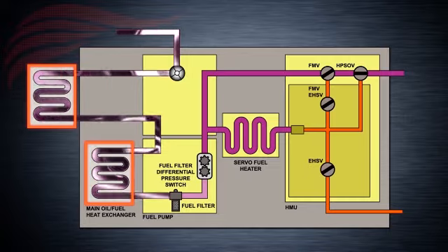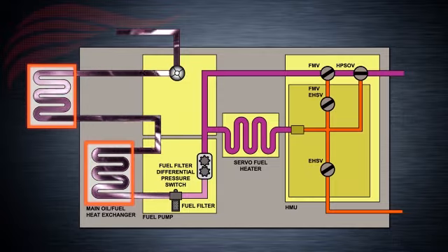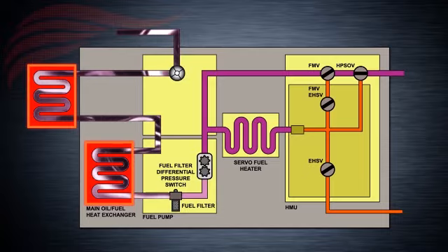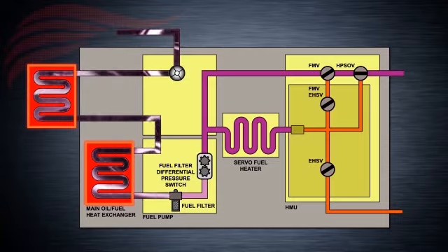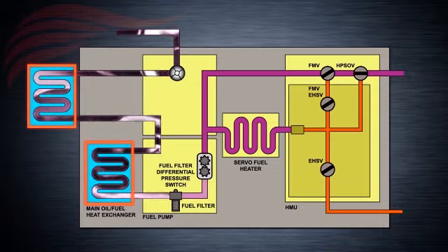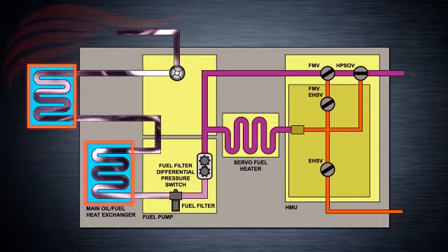On the other hand, in order to lubricate moving parts, engines have oil. This oil gets very hot during operation and it must be cooled. The best solution to this problem is to exchange thermal energy between hot oil and cold fuel so that oil becomes colder and fuel becomes hotter.